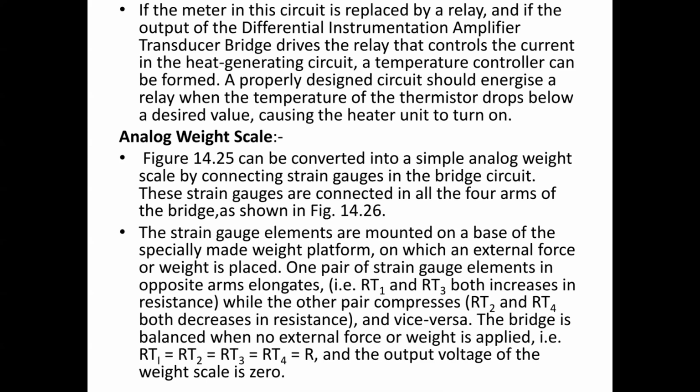So if you replace the meter with a relay, the output of the differential amplifier is going to drive the relay, which controls the current in the heat generating circuit. Then it becomes a temperature controller. This is the way we can make that circuit either a temperature controller, or measure the physical quantity, that is, measure the temperature.